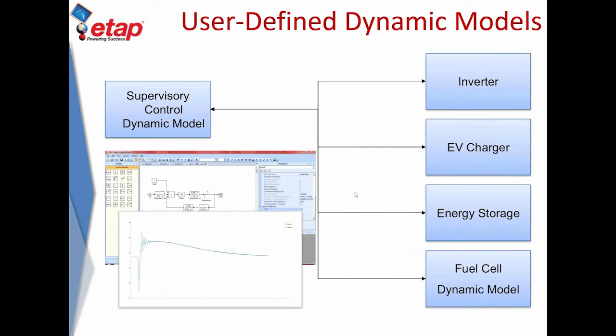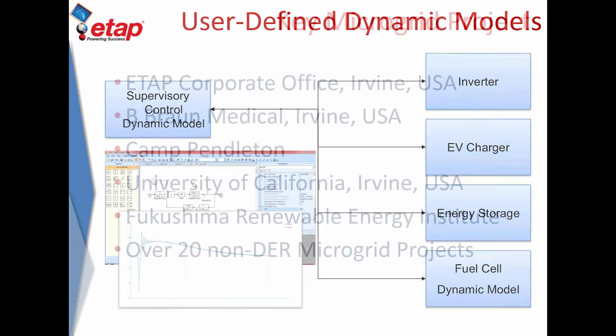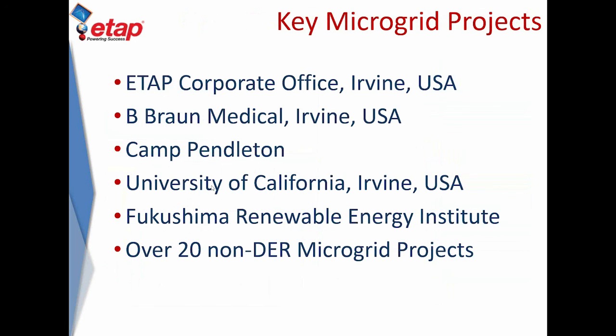So when we actually deal with generation optimization, we also have a supervisory controller similar to this that you can specify the proportionality gains and the time constants and adjust or tune this transfer function to behave in a smoother manner. And what I mean by that is for any small change in the system, there shouldn't be any drastic corresponding balancing change. It must be gradual. So some level of tuning obviously must be done, and this is actually done inside the study case again, where the control strategy is defined.